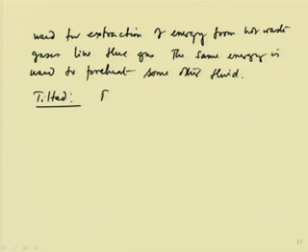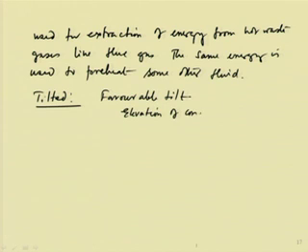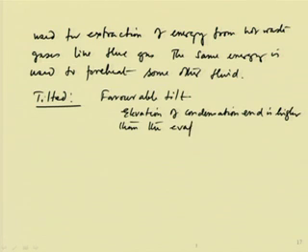So, one is called favorable tilt. In this case, the elevation of the condenser end, the condensation end, is higher than the evaporation end. Then what will happen? The liquid will try to come down due to gravity.